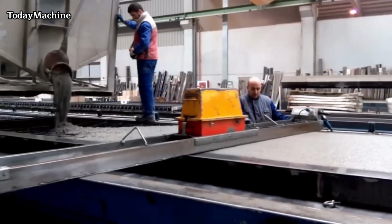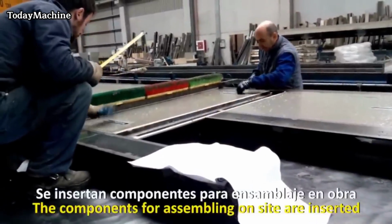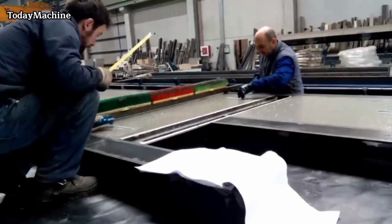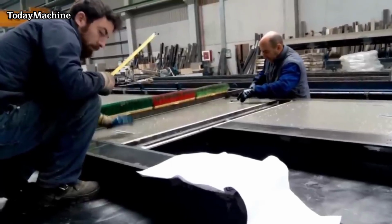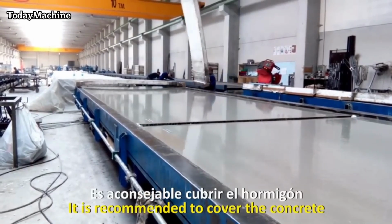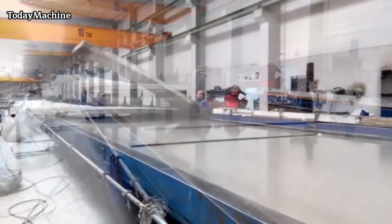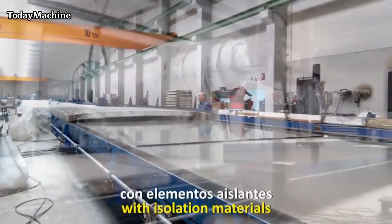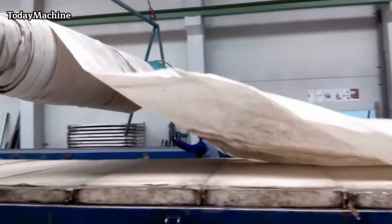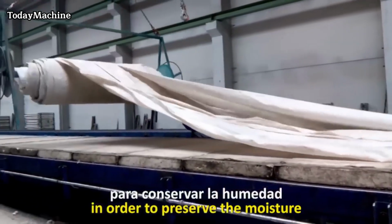Following the placement of handling nails, the manufacturing process proceeds with the vibration of the tilting table and screeding. Vibration is applied to the table to remove air voids and ensure that the concrete is uniformly distributed throughout the mold. This step helps in achieving the desired density and strength of the panels. Screeding, on the other hand, levels the surface of the concrete to achieve a smooth and even finish. Both vibration and screeding are critical for the overall quality of the precast panels.